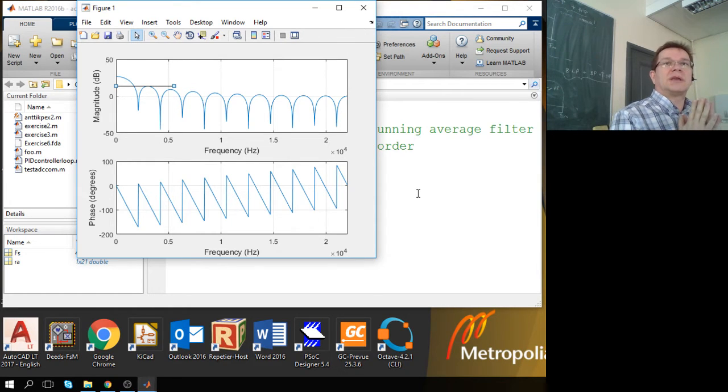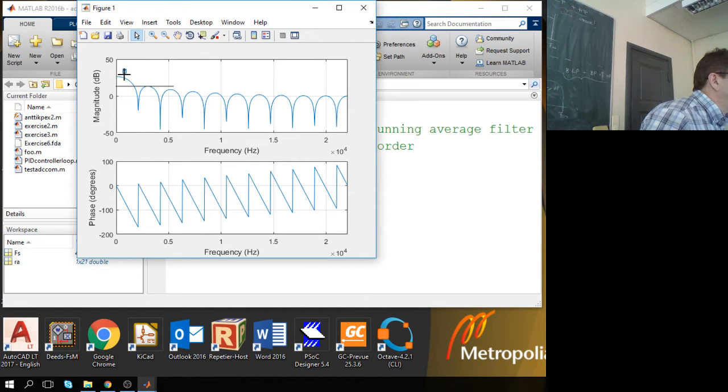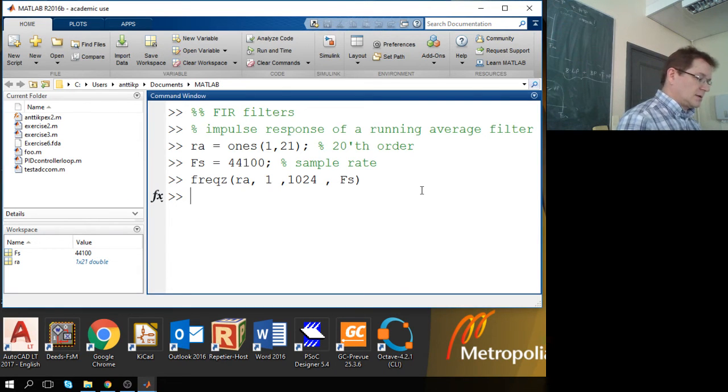First, I would like to check if I can make a cutoff frequency, which is defined somewhere in here. You have minus 3 dB points. Yeah, it has a nice cutoff frequency, but on the other hand, the stop band attenuation is not that great. But let's first fix the cutoff frequency, say up to 4 kilohertz. 4 kilohertz cutoff frequency, and use the sinc to do it.